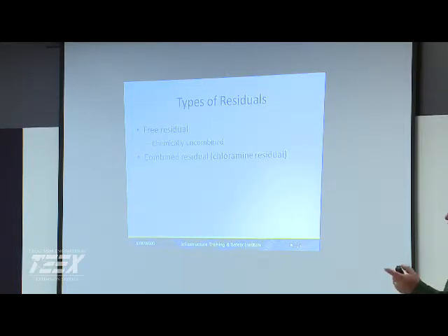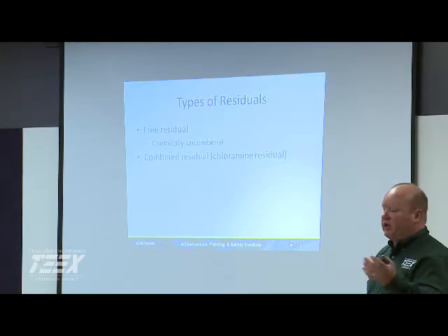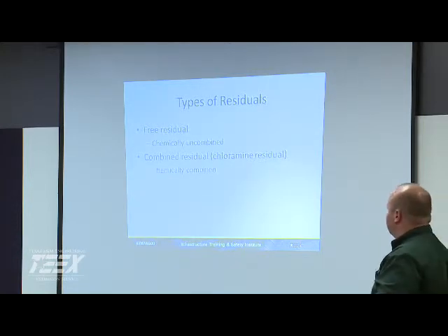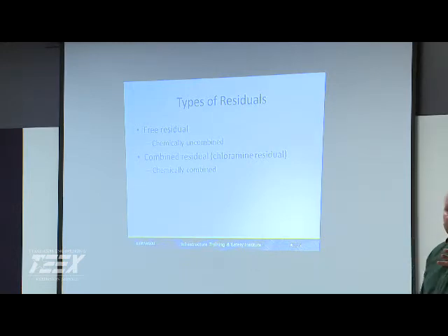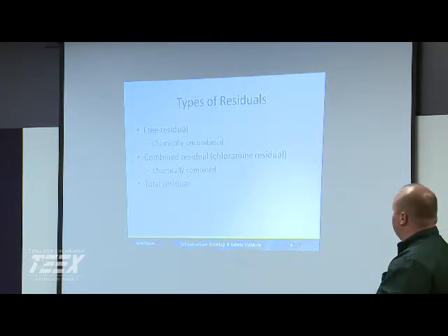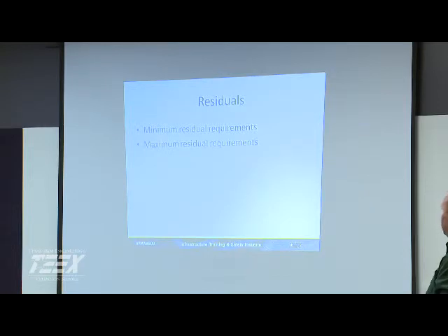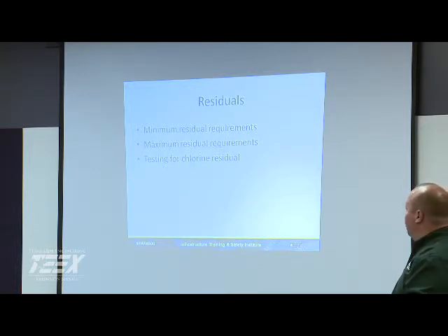We're looking at residuals. If y'all are just using chlorine, you're looking at free. In Texas, if you're using surface water, you're combining it typically with ammonia, and so you're going to look at your chlorine residual. I'm used to free, or in the wastewater, you're looking at total, is what you're normally looking at. So that's your free and your combined added together. We have our minimum requirement of 0.2. Your maximum is 4.0.